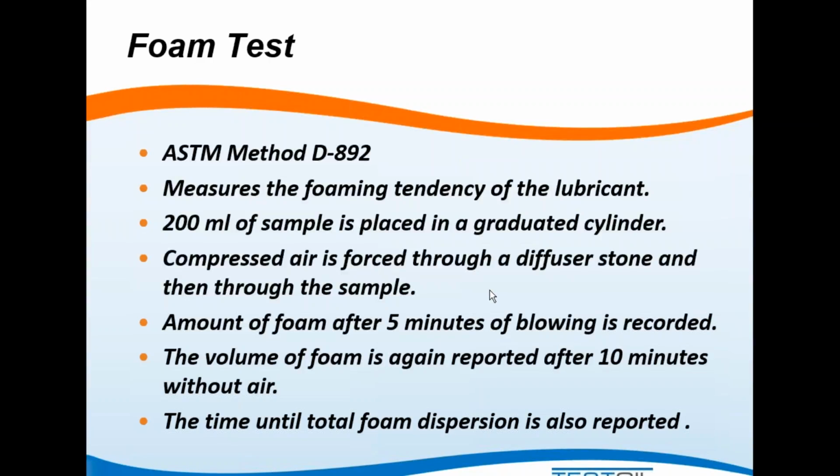That being said, as I've taken a look at turbine reports over the years, you get a lot of them that don't even get a foam layer. You get to the end of 5 minutes, and there's no layer of foam. The test is done at that point. And then you have some that have foaming issues where you get to the end of 10 minutes and you still have the foam layer.